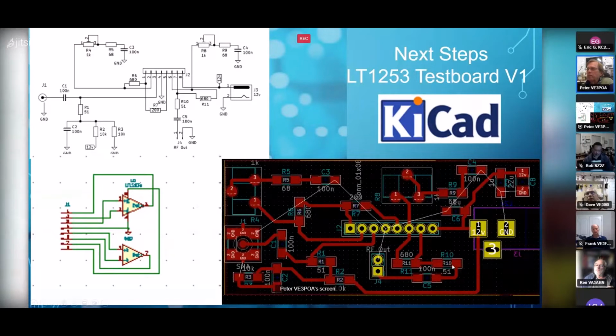The other problem I had was this pin header was on the top of the board as well, and the pot for the second stage of the op amp was here, and fortunately I had a trimmer that had the adjustment on the side, because after I finished everything, I realized that the breakout board would now sit right over top like that. So that made it a little bit awkward. So the second version has the pin header underneath, so that I have easy access to the adjustments.